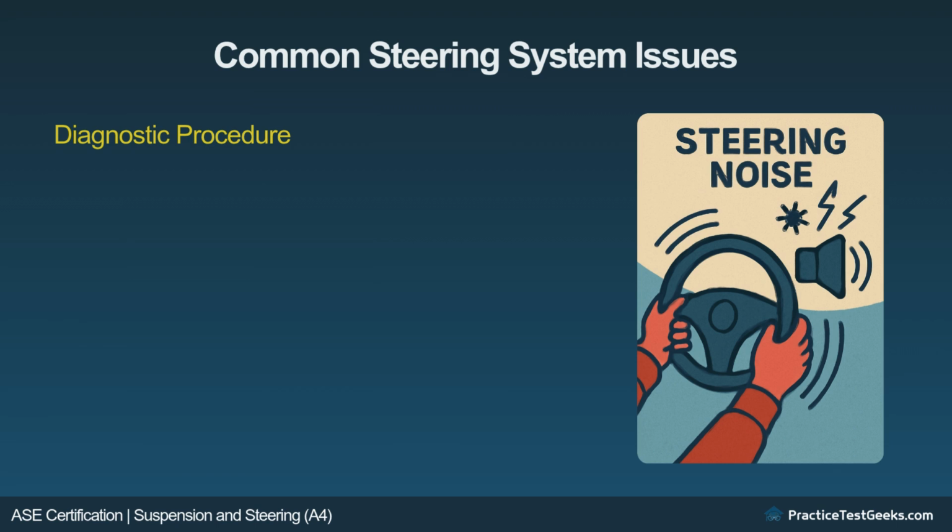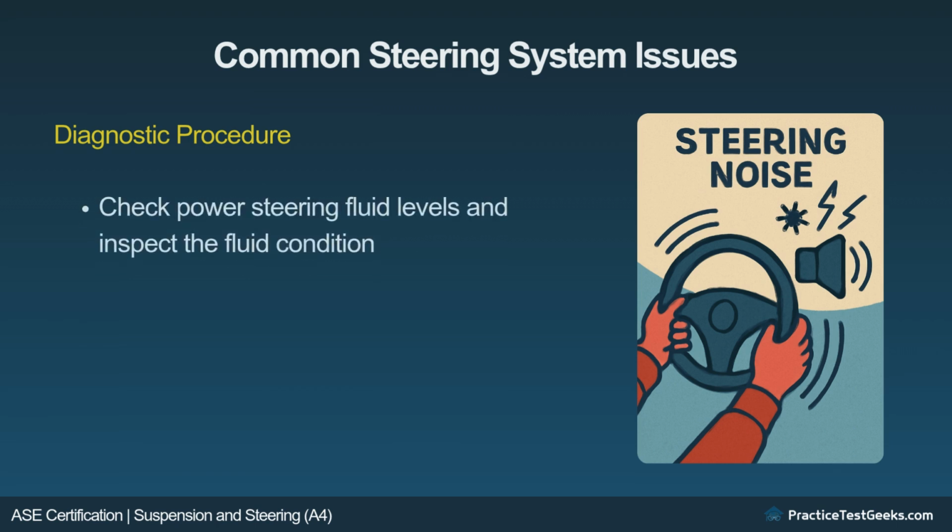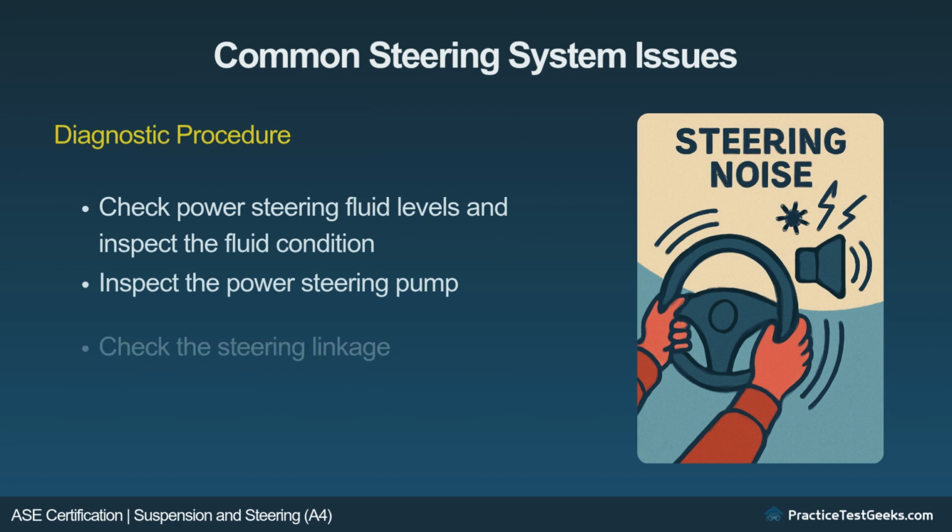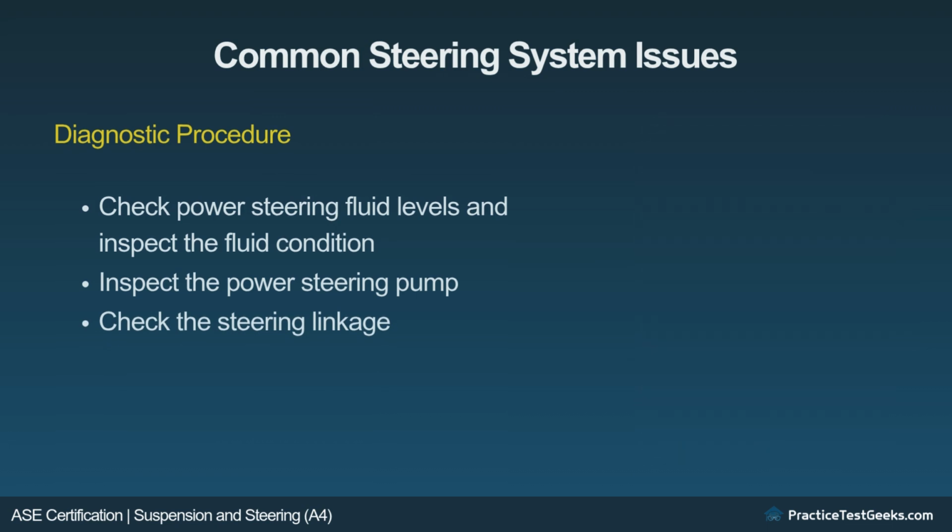Diagnostic procedure. Check power steering fluid levels and inspect the fluid condition. If it's low or dirty, flush and replace the fluid. Inspect the power steering pump for signs of wear or failure. Check the steering linkage for worn components or loose parts that could create noise.